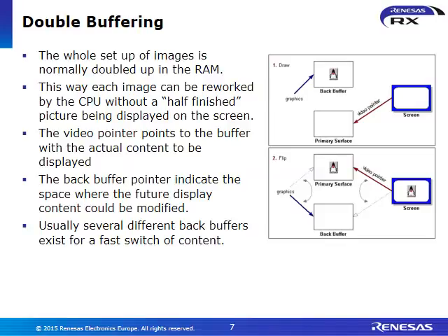That enables you to make quite nice transitions between different pictures, where you don't see half-finished pictures on the screen by accident. So that's the concept you usually take care of for HMI. You usually need a double buffering concept. You can get rid of it if your image on the screen is quite stable, quite fixed, and not changing much, with not so many animations. But double buffering is really recommended.